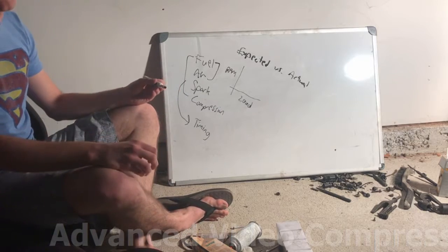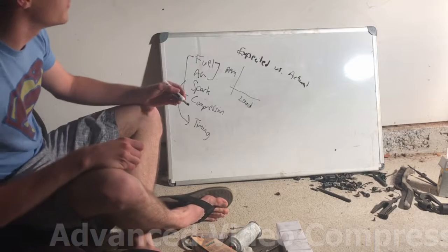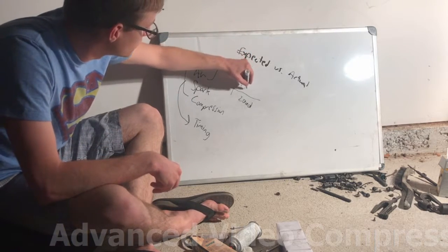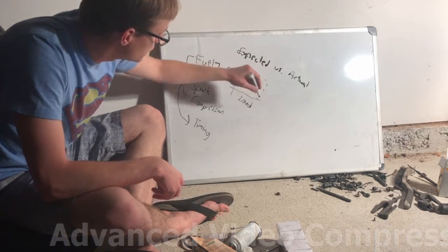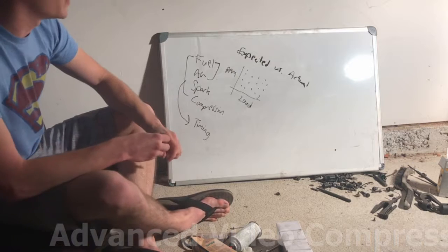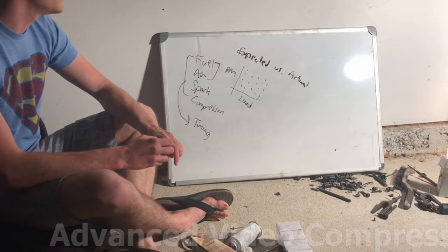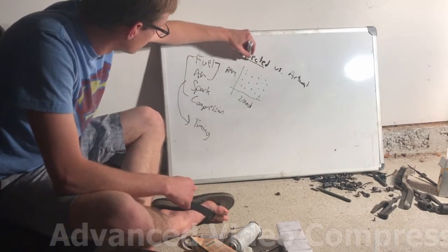And through experimentation and testing at the research and design facility for the automotive manufacturer, they're basically going to come up with a table of values that are going to tell them the expected values the computer should see at laboratory settings for any given RPM and load combination that the engine sees. So this covers the expected part.